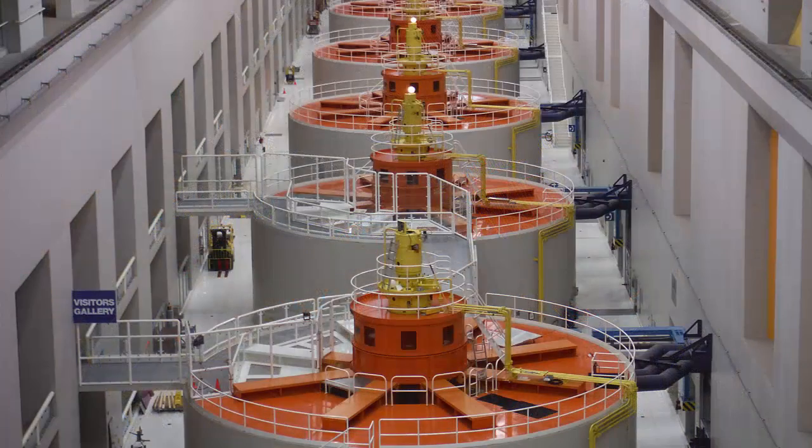On the generator side of the equation, the synchronous generator is what produces most of the electricity in the world today. If additional generators come online, they must first be synchronized to grid-appropriate voltage, frequency, phase sequence, and phase shift using a synchroscope.